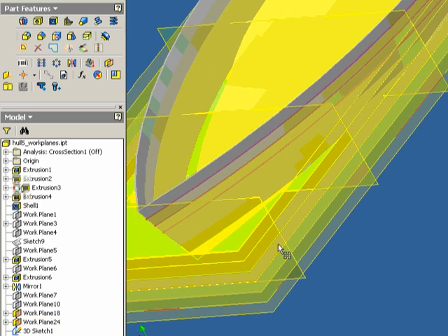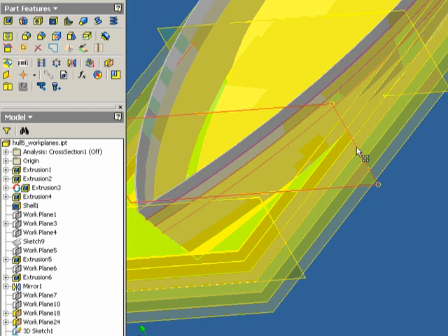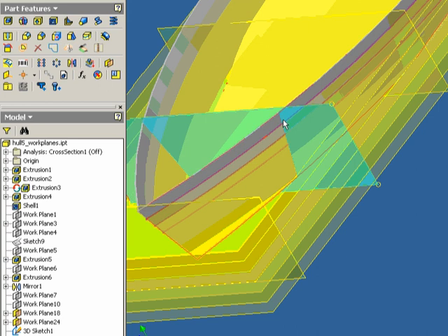Alright, this is station area 0. And of course all your half breadth values are going to be 0 for this one. Station area 1, we need to create a work point that's going to be the intersection of this plane and these lines. And I'll show you how to do that. So I'm just going to hold on to the control key, and I'm going to press station area 1. And you see how it passes through the hull of my boat. I'm also going to hold the control key down and select that red line we just created.